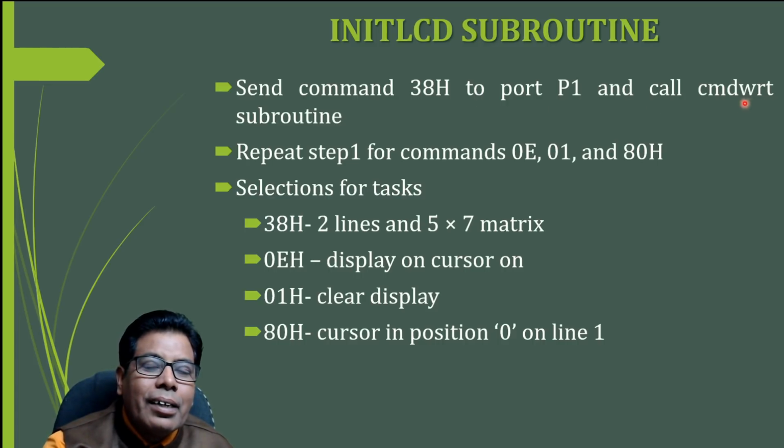So the command write subroutine will always write the command to the LCD. Here we'll send the command to port 1 and then call the command write subroutine. So the first command, the code for the first command, that is 38, will go to the LCD. Then repeat step 1 for commands